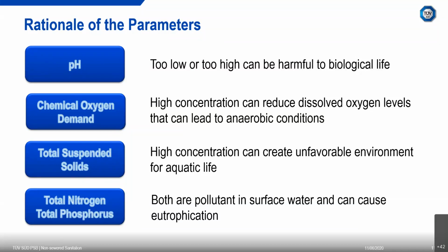TSS, or total suspended solids, is a measurement of the total solids in a water or wastewater sample that are retained on a filter paper by filtration. If TSS is not removed properly, high concentration can lower the water quality in the receiving environment. The suspended solids absorb light, causing an increase in water temperature and decreased oxygen, which creates an unfavorable environment for aquatic life.